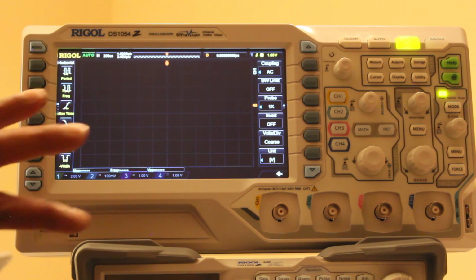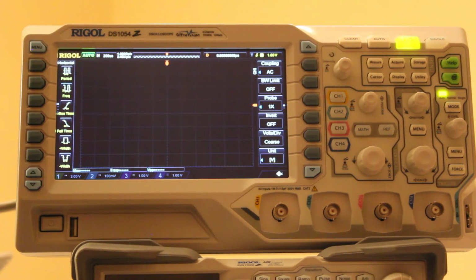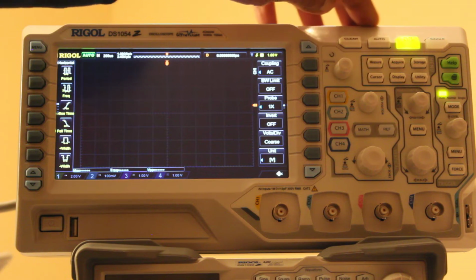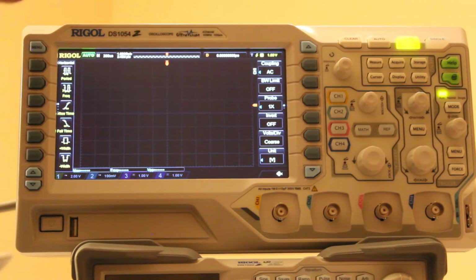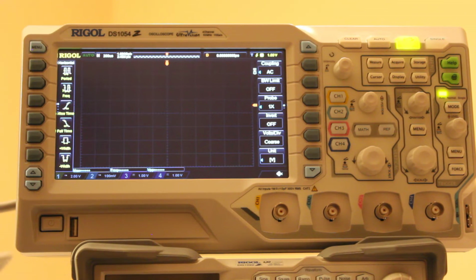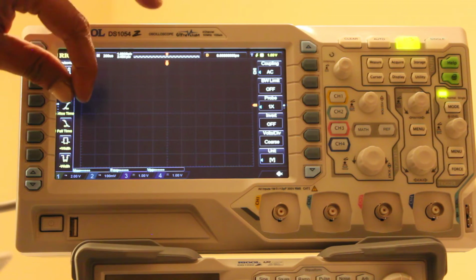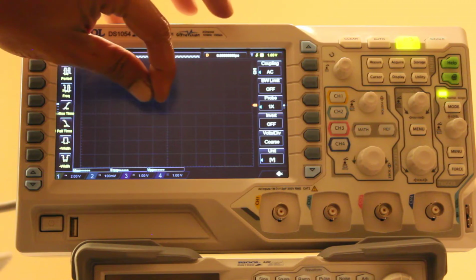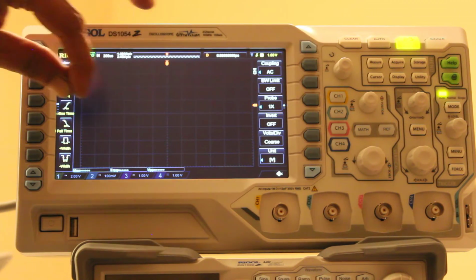Right now there is no signal coming, we're not measuring anything. This is running automatically. When you want to acquire data, that will acquire data automatically. And in the very top, you'll see somewhere it's written H, and following that it's written 200 US. So U is standing for micro, so this is 200 microseconds. So each division is 200 microseconds on the x-axis.